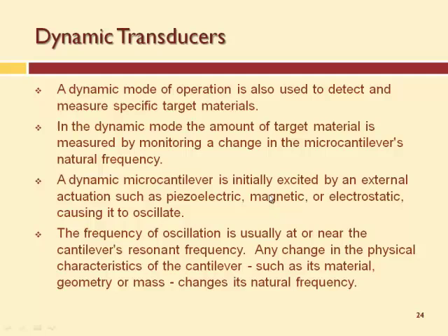So you can get a microcantilever to vibrate by exciting it externally. So you can have an actuator on there that causes it to vibrate. Piezoelectric transducer you can use. Magnetic fields you can use if you have the right materials. Electrostatic was the most common.